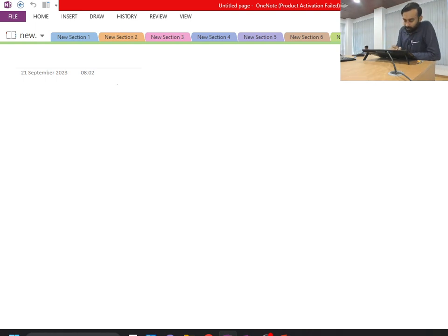As I told you, the definition of linear momentum is m into v. Okay. So for this case, if I write in vector form, then I will be writing m into v vector. Now we can see from here that our B is nothing but equal to m into v vector, and beta, which is the intensive property per unit mass, comes out to be v vector over here. Okay.